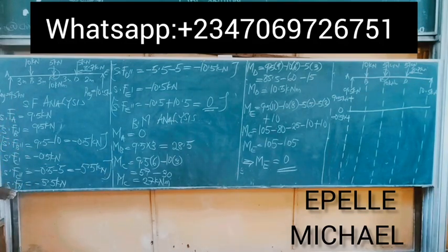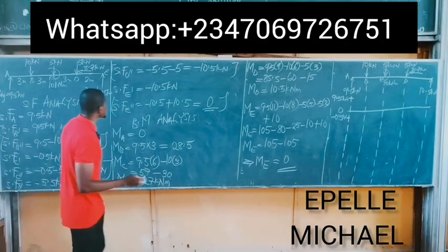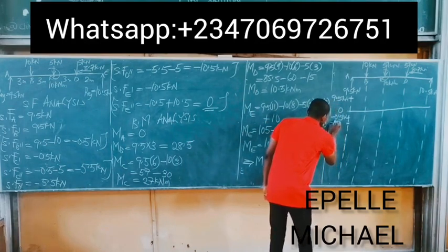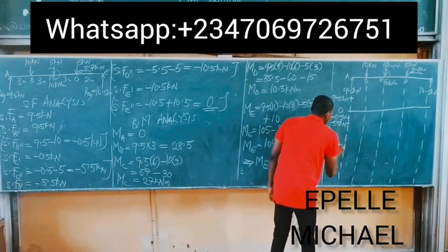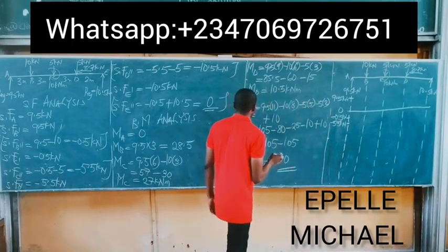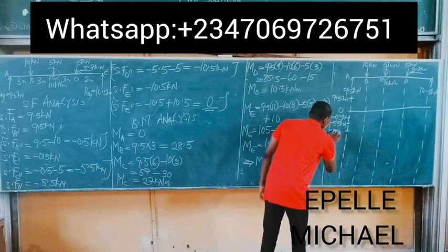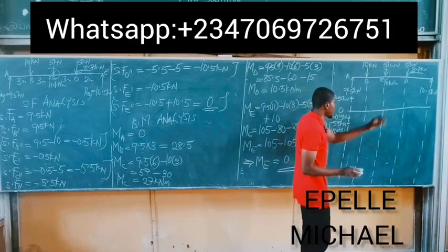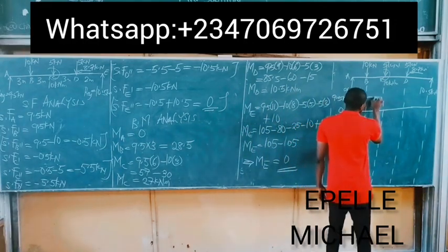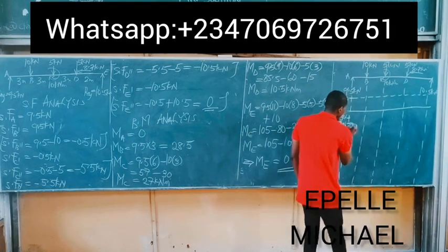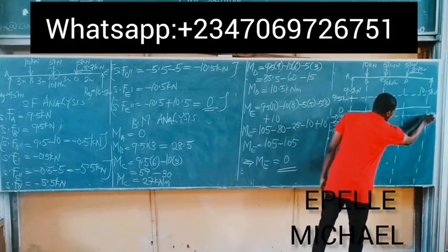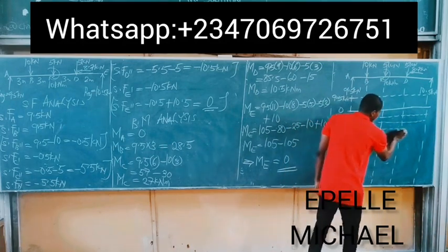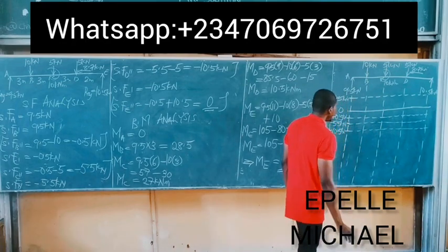Next, shear force at C prime prime gives us minus 5.5. That's the next lowest, and you indicate that here, minus 5.5 kilonewtons. Next is minus 10.5 kilonewtons, and finally we have 0. So this is the 0 mark. All you do is trace out these points, the values of this shear force, to the end. So this is actually a freehand sketch.